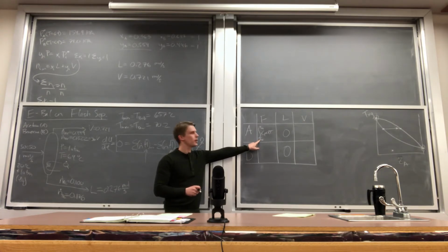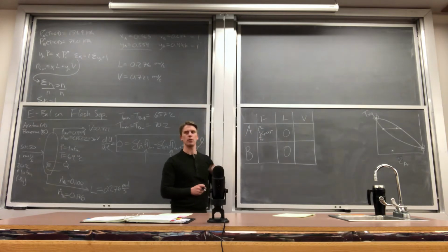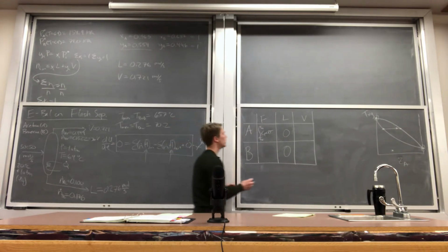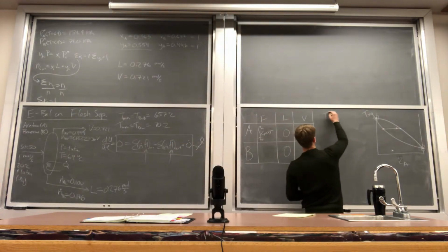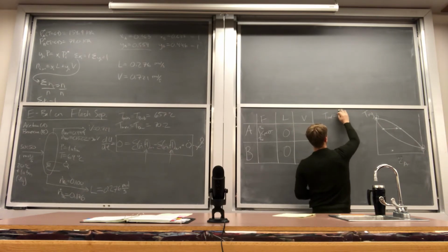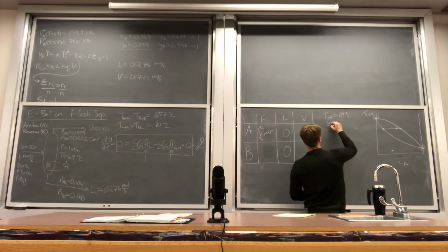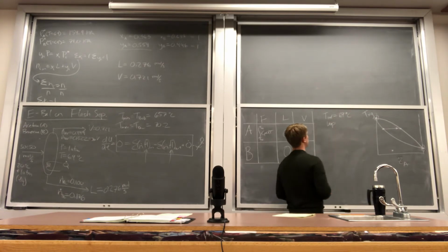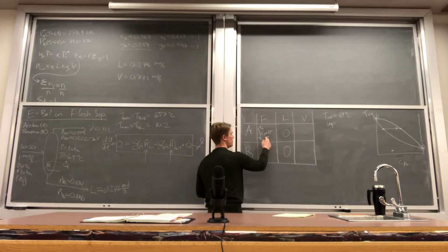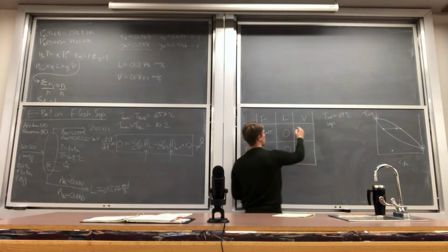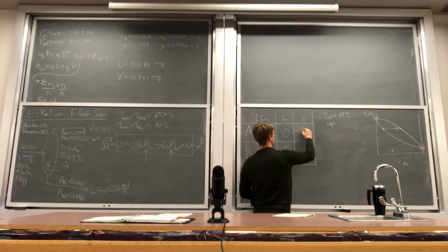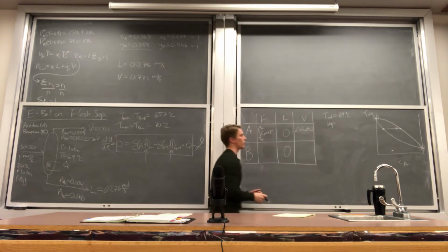Right, your reference temperature is actually at a higher value than your inlet conditions. So here I could write out T ref is equal to the vapor temperature. So we would expect this to be a negative number. And for here, this is just the heat of vaporization at the reference temperature.